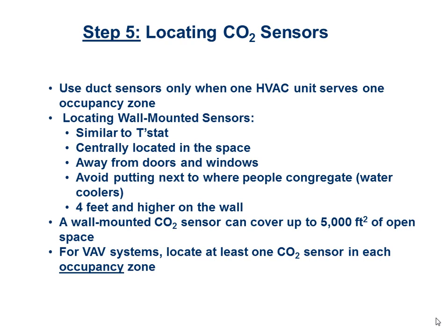CO2 locations, like I hinted to earlier, return mounting should be avoided. The only place that a return air sensor for CO2 would make sense is if the air handler is serving one giant single open space. So if you have one rooftop unit serving a school gymnasium by itself, that might be a good idea. If you have one air handler serving a single movie theater, theater number 3, for example, that might be a good idea.